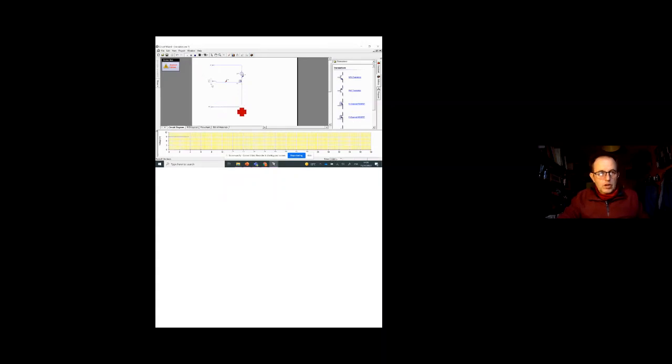Okay, here we go with an example of a MOSFET. So what we've got here is the voltage rising. Okay, so you need about 3 volts in order to turn it on. There's a turn on voltage. You need 3 volts to basically turn on a MOSFET. But then, as I said, the linear region is really sharp, and so it saturates really quickly.